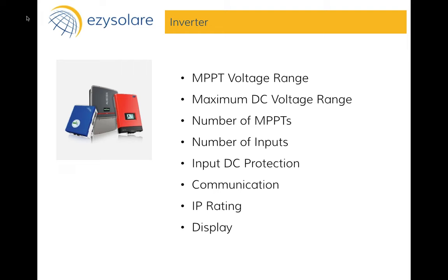The second thing that you should always check is that the tolerance level provided by the supplier is only positive. It's not too uncommon to see the module supplier, in his specification sheet as well as in the order, request 250 watt peak plus or minus 5%. What you need to ensure while you raise a purchase order to the supplier is that it cannot be negative. It should only be positive. A 250 watt peak panel can be 250, 251 up to 254.